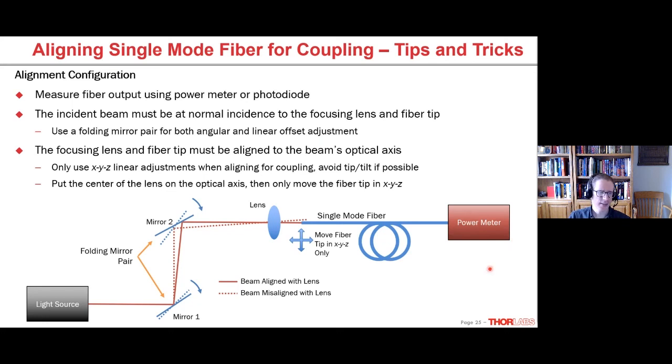So it is best practice for a lab setup using single mode fiber, most people like to tape down the fiber so it doesn't move from day to day or experiment to experiment. That's a best practice in case you have cladding modes, or, for instance, if you bend the fiber, you can get polarization effects, which we want to avoid. So if the fiber is going to be used bent, keep it that way. If it's going to be used straight, keep it that way. Theoretically, though, that fundamental mode of the fiber is relatively bend insensitive. I know that's a long answer, but hopefully it's helpful.